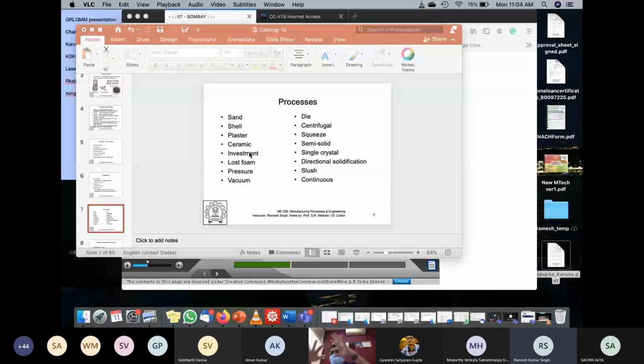It's not a solid box, but just a shell of whatever shape you want. So that's why it is called shell. Similar process, just you use a resin to create a stiff, thin shell which will create a cavity of whatever part you want. Does it make sense? You got shell, right?